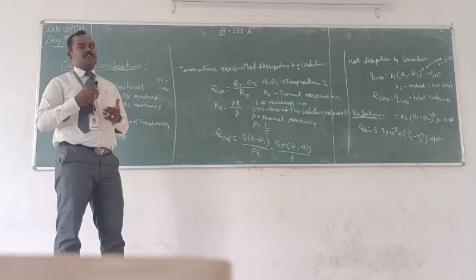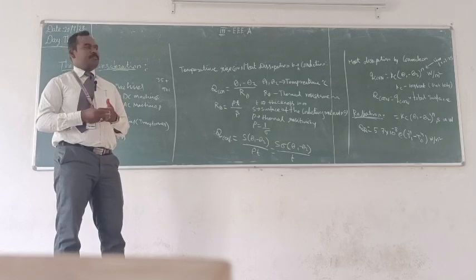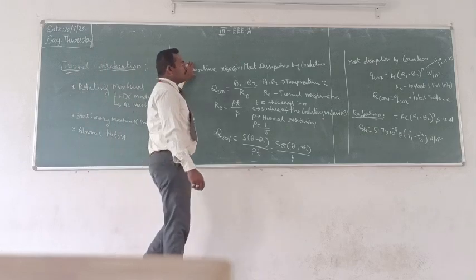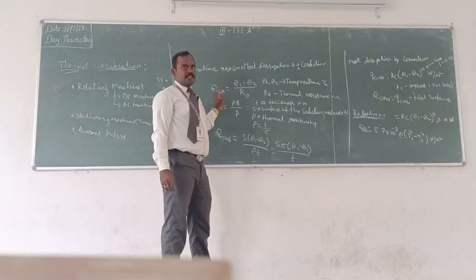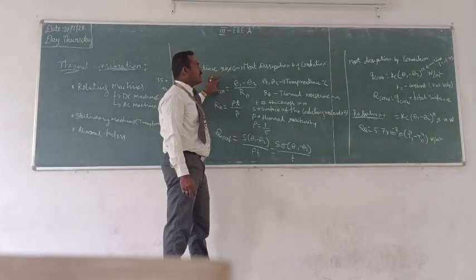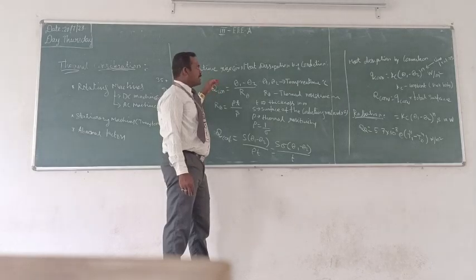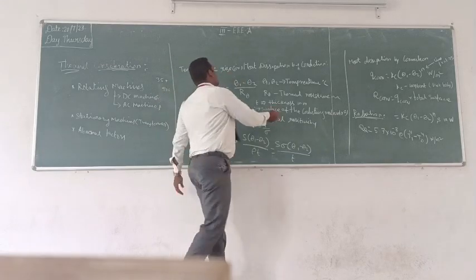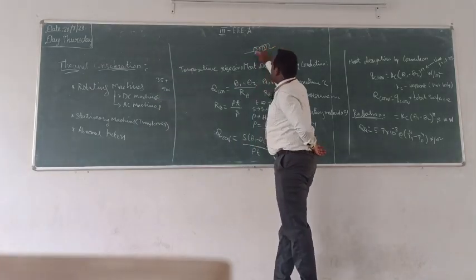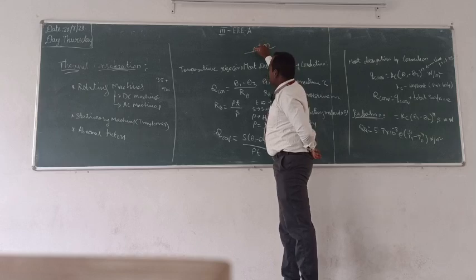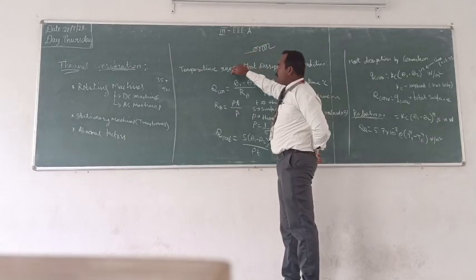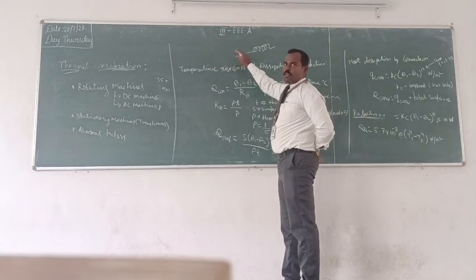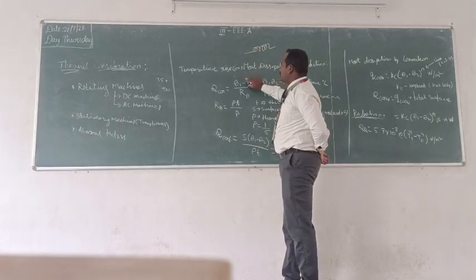So the developed heat, how it is transferred from one medium to another medium, there are three processes that we also keynoted in the last class itself: conduction, convection and radiation, right? Conduction, in the sense, you can put any steel rod or any material or any winding from one conducting medium into another medium. That means you can consider any coil like this. If heat is developed, it has the conducting part. So heat is also conducted from one location or one part into another part. That is the process of conduction.